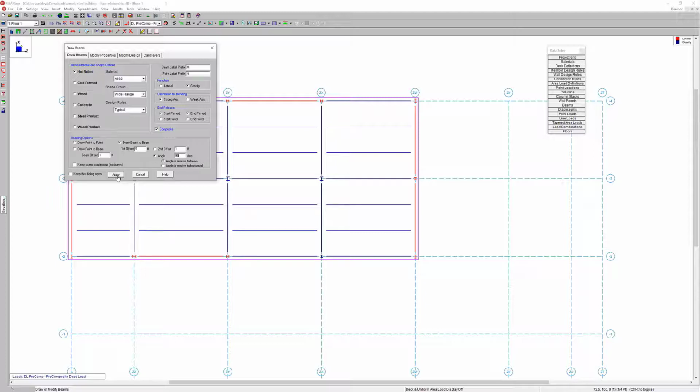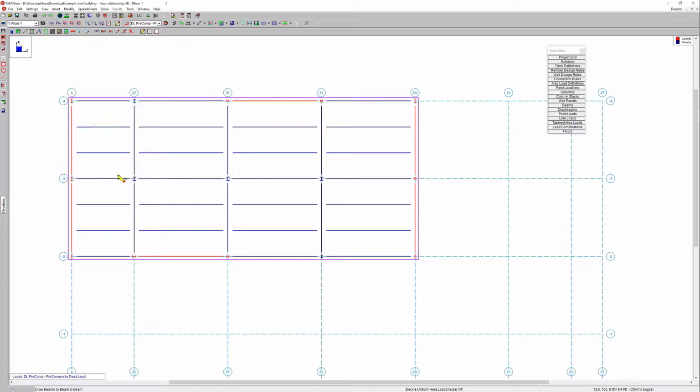And so that angle is going to be relative to the beam. Okay, so then I'm going to go ahead and choose to apply this on my floor level 1. So I'm going to select the beam. It went ahead and selected 5 feet offset. And then I'm going to select it to frame to this other beam. So that went ahead and did that 90 degrees at that 5-foot offset there.